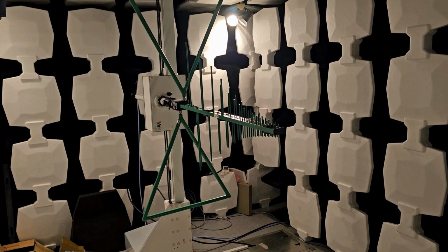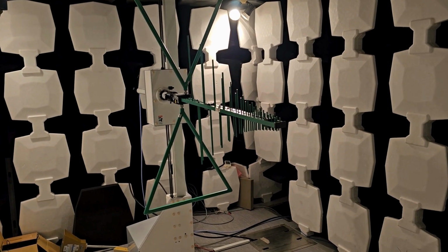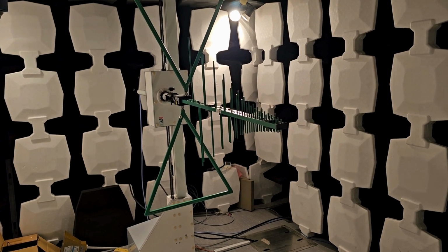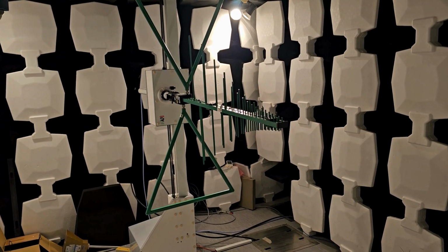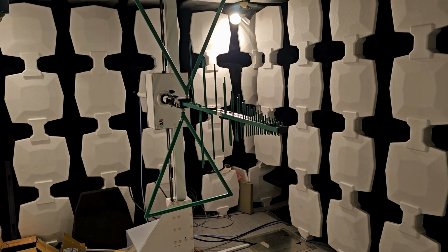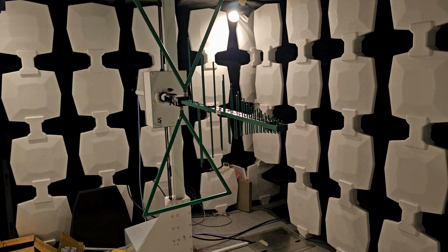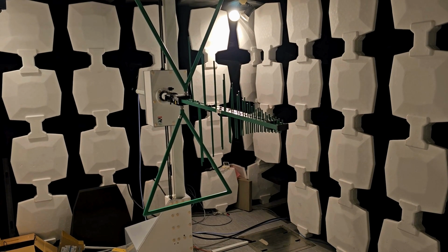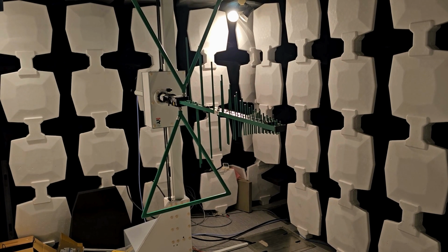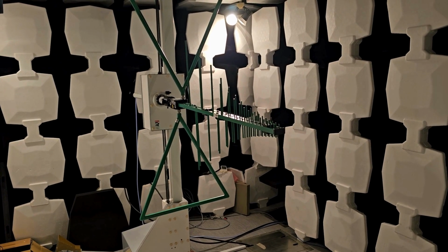So in short, the antenna will be hoisted up to do a pitch search, starting off from 1 meter. After they complete all the pitch search at all the frequencies, they will move up to 1.5 meter. Again, they will do all the pitch search. Then they will move up to 2 meter and do all the pitch search. Let's say if this chamber is 4 meter, then it will go from 1, 1.5, 2, 2.5, 3, 3.5, 4 meter, and finally all the results will be captured.